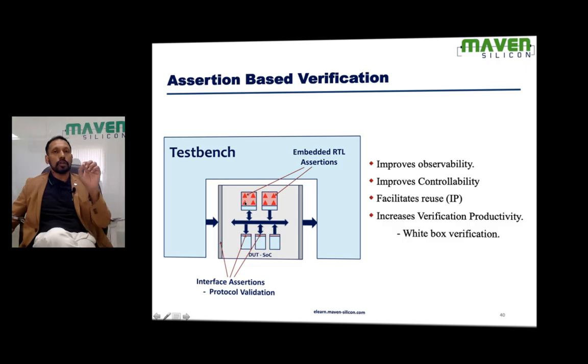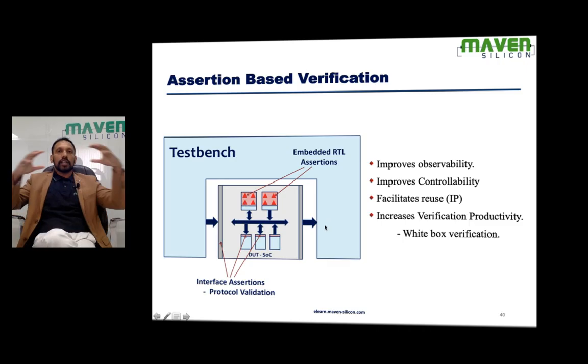So we would be able to identify the exact module. This is the particular IP. Within this particular IP, we have written some assertions for a particular component like decoder, and this decoder is not working properly. That's why we are getting this data mismatch. You are running simulation.